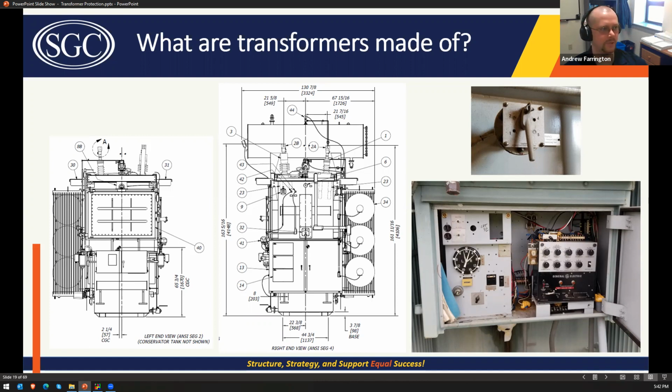You might change the no load tap, but the load tap can be changed under load, and it's usually regulated by some sort of device. All these dials here are where you're setting what voltage it's trying to use for the band center, and you've got a bandwidth, which allows the voltage to be anywhere inside that bandwidth.